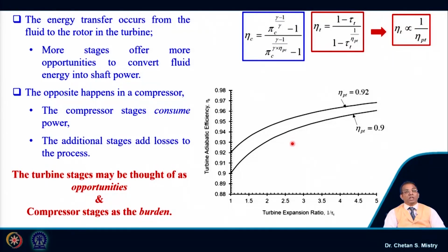Now, the situation here is we want to rotate our front fan at a lower speed. It has so many aerodynamic, aeroelastic, mechanical issues with the fan, and that is what demands my fan to rotate at a lower speed. In order to rotate that wheel at the lower speed, we are extracting less amount of work per stage by incorporating more number of stages. So, just try to recall this part, because that is very important to understand.